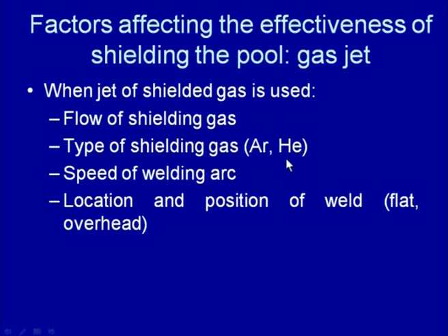However, there is a great difference in the cost of the shielding gases helium and argon. Helium is normally used for the welding of critical joints like in aerospace and nuclear reactors, and for most of the commercial applications and fabrication, like in pressure vessels, argon is commonly used.